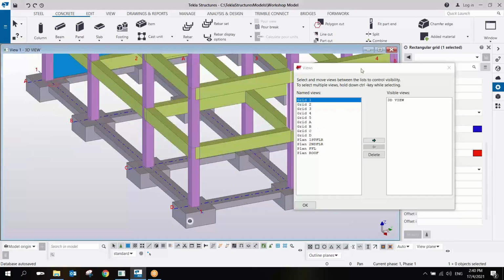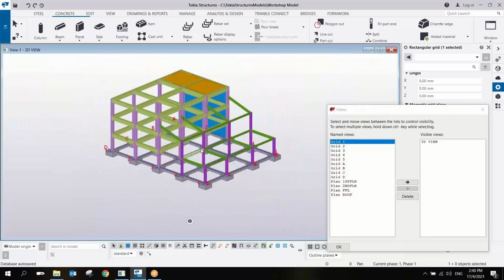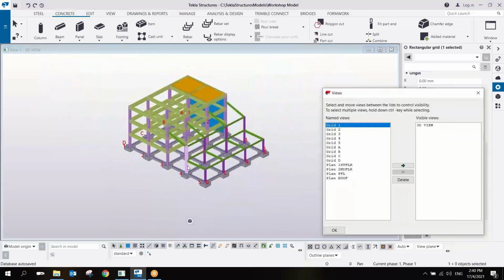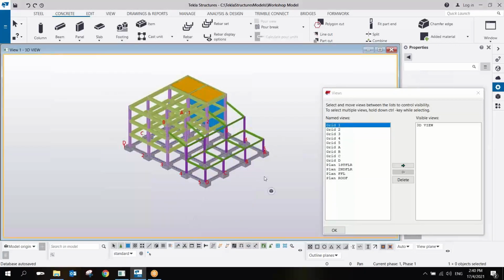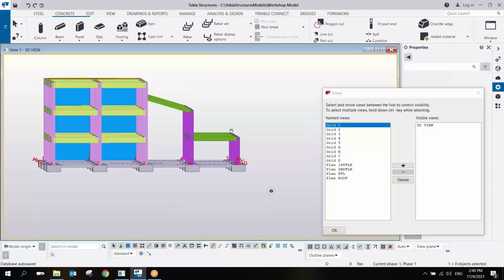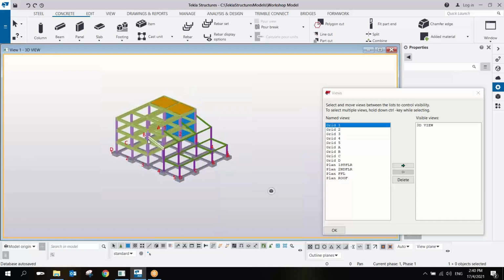All right. If you may ask, hey, why don't we just modify the grid line according to the movement? Yes, you can do that, but it will be much faster if you recreate the grid line by simply delete and create again the grid line. So that one is a much faster way of dealing with this view.